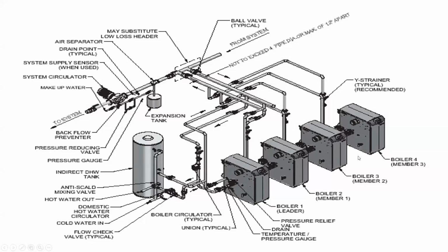And so whenever the inlet temperature is the same, if it's coming back at 170 and only one boiler is running, 170 is going, these three are off. If I get to that design condition where I need everything, it's the same temperature all the way across all of these boilers. So I'm not doing that. So I'm 170 to 190 all the way across the plant.